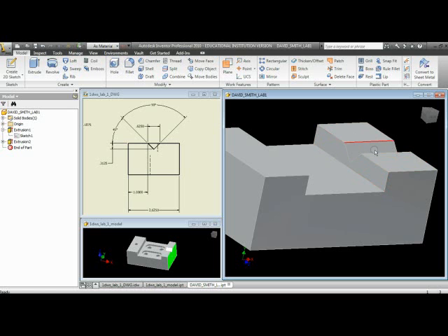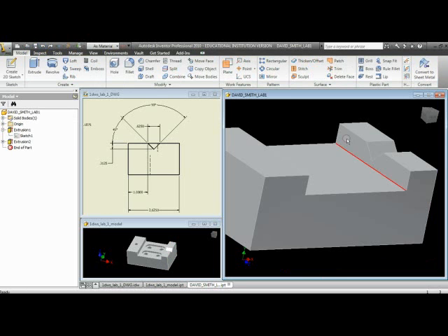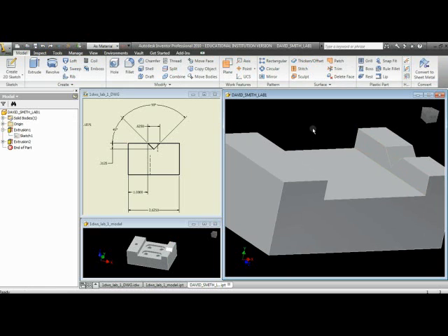Okay, then what we're going to do is do an extrude. Now I have to pick the profile because, as you can see, I've got this big profile, I've got this one, and I've got that one. It's starting to shoot out this direction, and that's because it was in join mode by default. I want to hit cut, again that Boolean operation. Once I do that, it flips the direction.